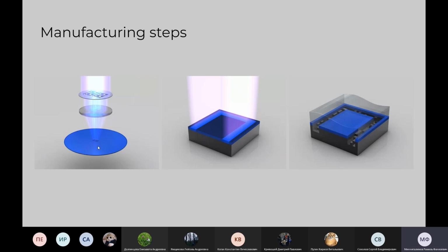The next step is exposure with ultraviolet rays. This part will be revealed later, but I can say that at this stage the anti-reflective finish will be exposed to ultraviolet light. The chemical reaction activated by this light is similar to what happens to film material in our camera as soon as you press the shutter button. The areas of contrast material on the wafer that have been exposed to UV will become soluble. Masks are used as templates, and with ultraviolet light, it creates different circuit patterns on the wafer.